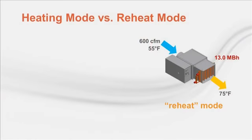In this mode, this coil is functioning as a reheat coil. This reheat load is highest when the net cooling load in the zone is 0. That is, the heat loss through the envelope balances with the heat gained internally. As depicted on the right, at this condition, the air is reheated from 55 to 75 degrees for this example.